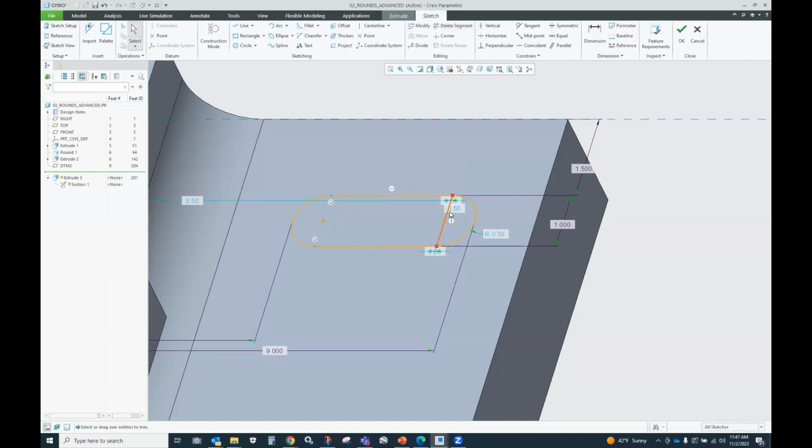I created my new geometry, and rather than deleting this, I want to remap my IDs. Now that's arc 25, that's one, and that's 28, 25 and 28. Now what I'm going to do is pick on this 25, and I'm going to replace it with 28. It's giving me a warning saying that the dimension scheme can't be recreated, so I'm fine with that. But watch what happens there now. That line is now ID 25. A moment ago, it was ID 28, right? So I just remapped the ID from 25 to now be what used to be 28.